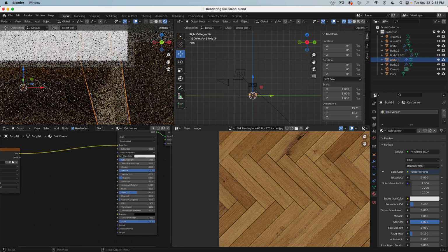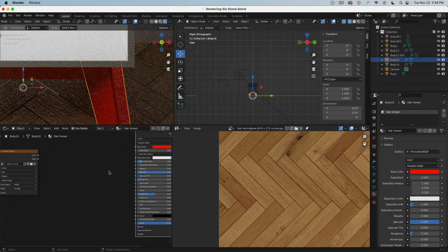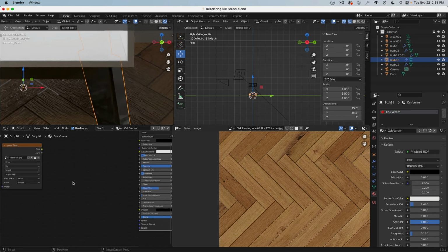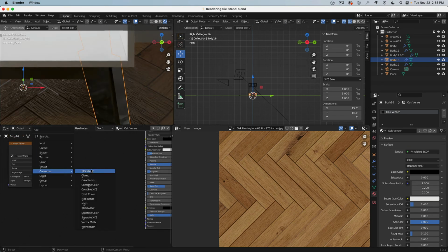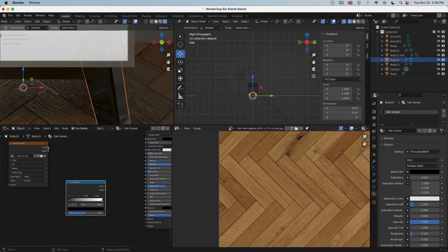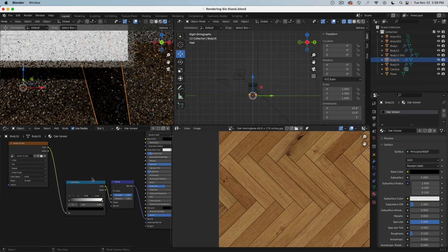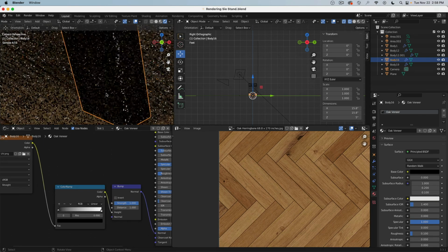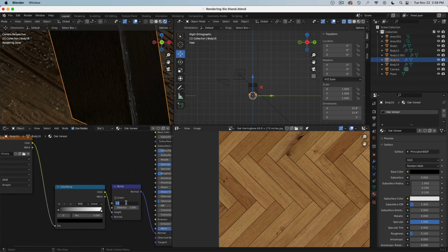Let's make this super reflective. Turn this off so we can see actually how this works. I make this black so the reflection is perfect, easy to see. Color ramp, okay, and then this into the color ramp and bump. Zip. The nice thing is, at the beginning this might be a little bit confusing, but over time you start noticing it's always the same steps.